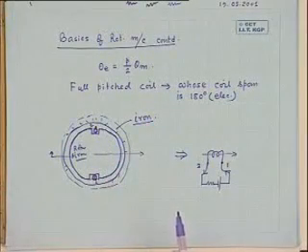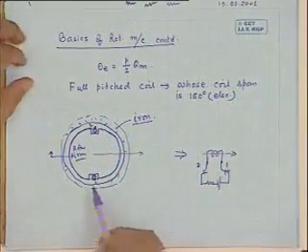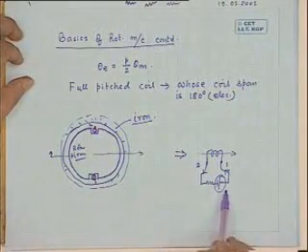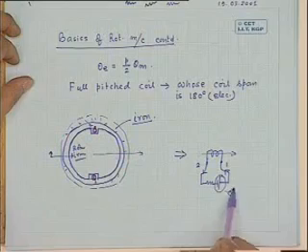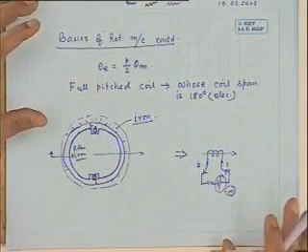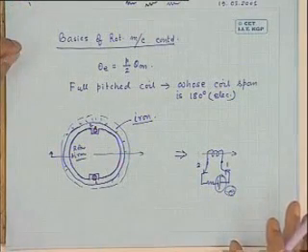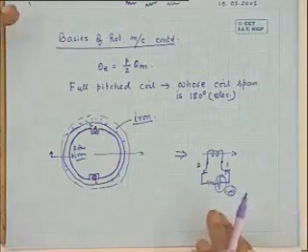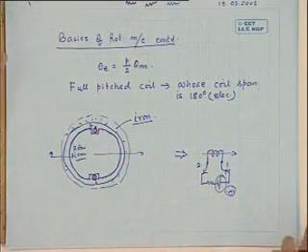Okay, you tell me, suppose in the first example, that is the simple single coil case, that is this one. If instead of direct current, if I excite the coil by alternating current, if I replace this current, instead of DC, by some AC source, what do you think the field distribution will be? Exactly, it will once again remain rectangular in nature.